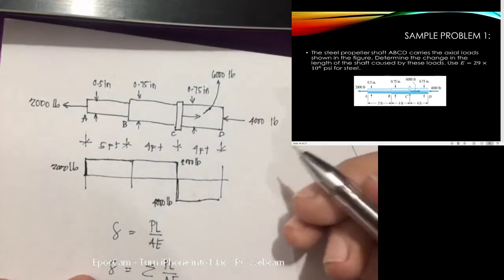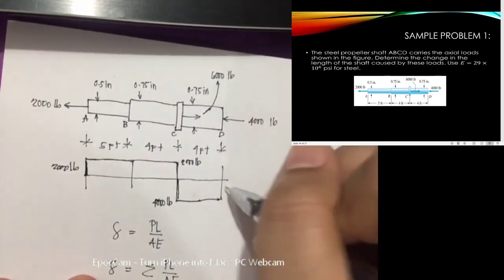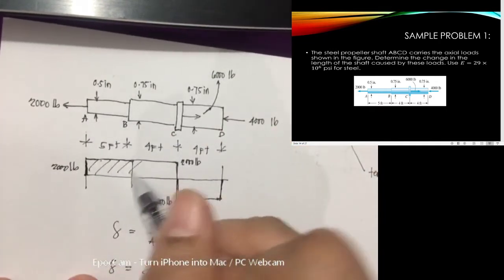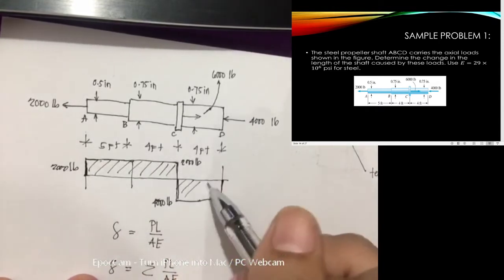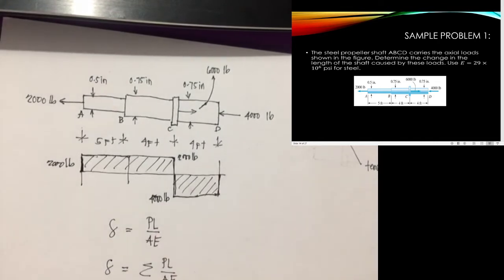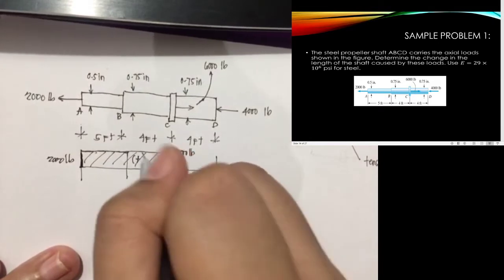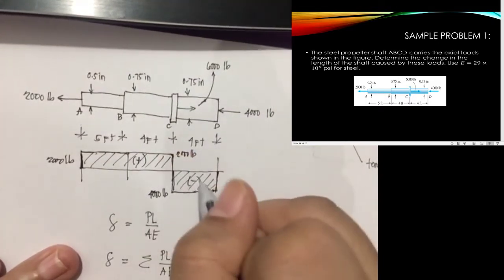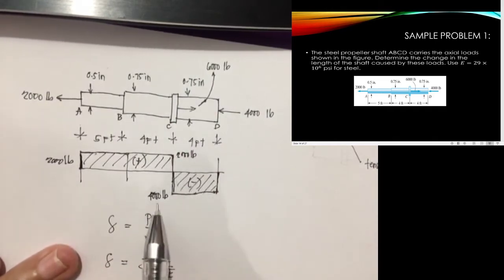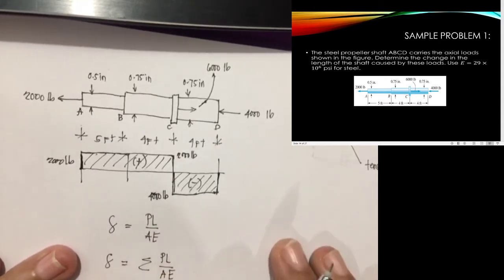We went down earlier with 6,000. Now, 4,000 opposes it. So, 4,000 goes up. So, that is your diagram. Here already, class, we know whether it underwent tension or compression. When positive, like this, it is in positive. So, meaning to say, your A, B, C is in tension, while your CD is in compression.